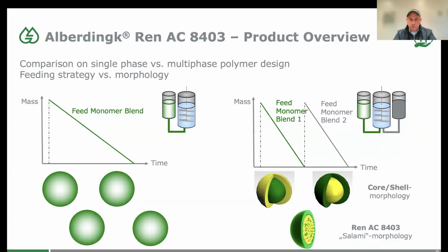So what happens here with the particle on the right-hand side? If you put them all together, they will start to form a film. So the particle boundary will be lost, and you will have one uniform film. And then you could think of it like the green material will flow away during film formation. So it will create a kind of a lake of molten material, because the TG is below room temperature.